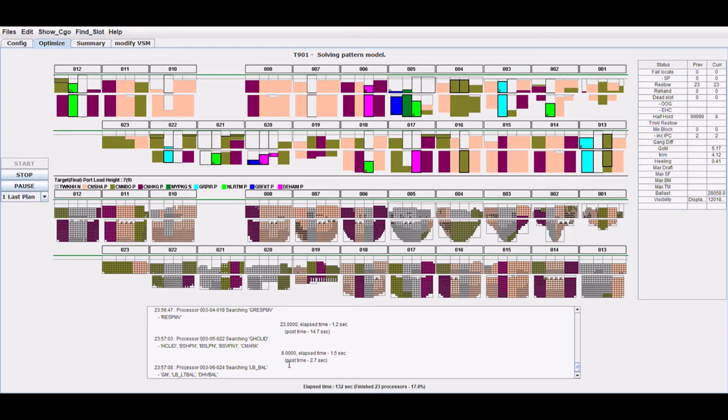This process is repeated for all ports from Kaohsiung, the first port on the route, to Port Kelang, the last port. Once the evaluation process for the block pattern of Kaohsiung, the target port, has been completed, next the engine will repeat the similar evaluation process for Shanghai, Ningbo, Hong Kong, and Port Kelang. Through this evaluation and feedback loop, the optimization engine repeats the task of finding the optimal stowage pattern for the entire port of call, not only for Kaohsiung.